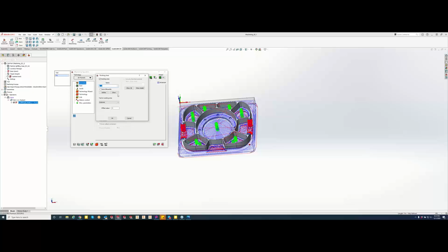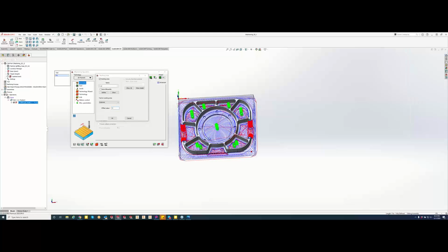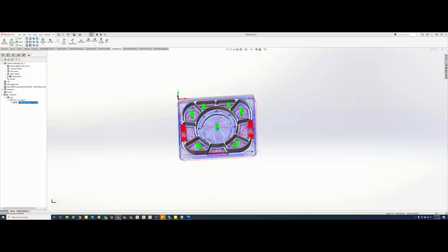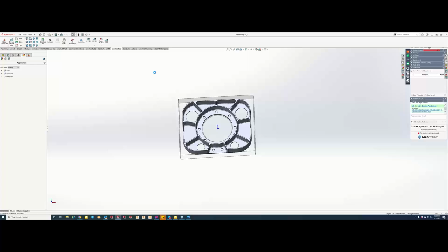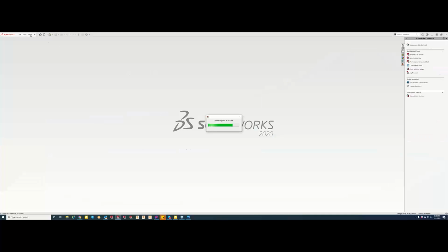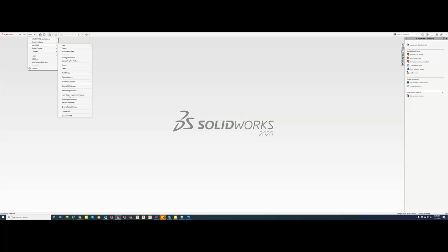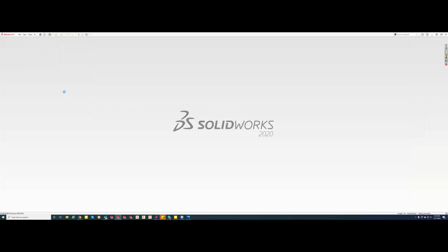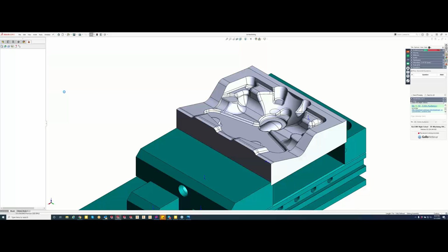And now we have a working area where the toolpath is going to stay contained to that working area as well. Now, if we need to go a little bit further outside, you guys can offset out the toolpath right here. So maybe our stock is varying a little bit on this part. Definitely set your external to a little bit larger, and then it will expand past as well. Yeah, the instances are going to be very rare where you want to do 3D iMachining on any specific part if you have material removal for a lot of parts. But just keep it in the back of your mind whenever you're deviating from the target model selection. Absolutely.